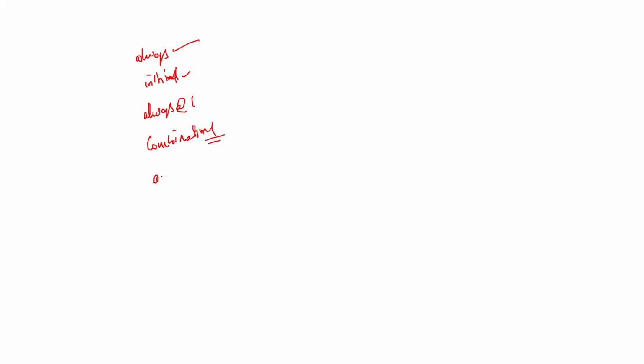So in combinational circuits, I am utilizing the assign keyword. Assign A equal to C and D, and B equal to X or Y. I am assigning that. These all are executed at zero simulation time only, because all are executing parallelly. Then I need to know who is executing first, who is executing last, and who is executing in the middle.